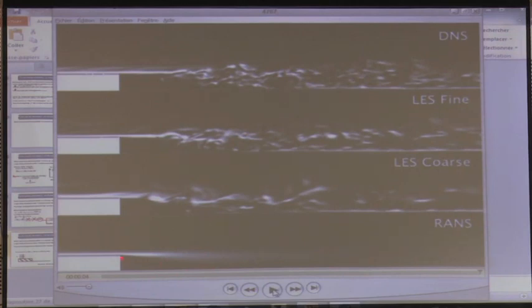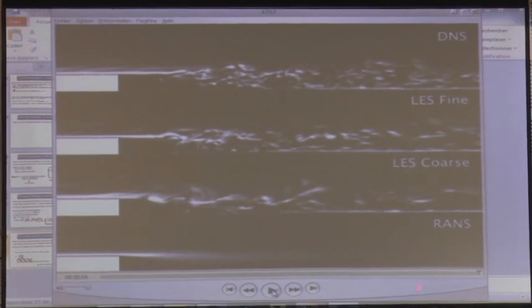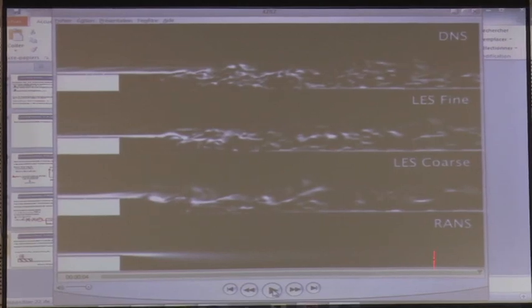You get the shape of the wake. You know that here you have an increase of viscosity, but here there's no more. There's nothing. No turbulence, nothing, compared to the reality where you still have a lot of information. So when you go from pure Navier-Stokes equations to Reynolds-averaged Navier-Stokes equations, you have to be aware that you are losing information. And it's not because the model is not correct. Probably that model would be the best that you can use for that. It's just because you are losing information when you solve the equations for the mean instead of solving the equation for the instantaneous flow field.